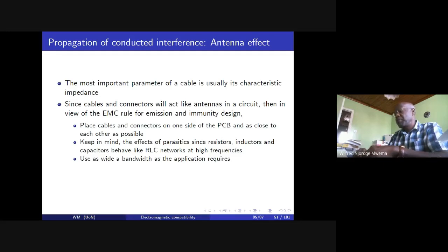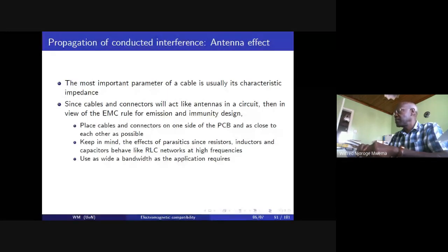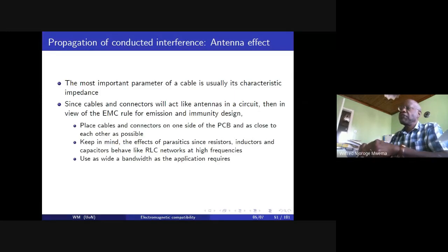Say, for example, if we are making an amplifier for a hearing aid, most of the information is intelligible up to about 3 kilohertz, and that's why the telephone line usually has a bandwidth of about 3 kilohertz. If you add more for broadcast, we just need up to 5 kilohertz. So you don't have to make that amplifier for the hearing aid go all the way to 20 kilohertz, because the person can hear all those.